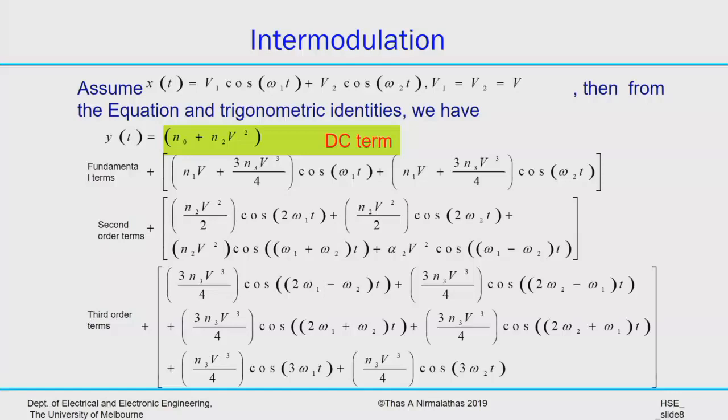Of course, if you design a circuit where the fundamental frequency and second harmonics are within one band, for example, a very broadband antenna looking from, let's say, 1 gigahertz up to 6 gigahertz, we want one antenna which looks at all the mobile systems and Wi-Fi and everything. Let's say we want to digitize everything out there and know who is transmitting what. That's a hypothetical situation. In that case, we want an antenna plus amplifiers looking anywhere from a few hundred megahertz all the way up to 6 gigahertz. So you can see 1 gigahertz and twice that, 2 gigahertz, is part of it, and even three times is part of it. In that case, second harmonic, third harmonic, even fourth, fifth become important, because all of them fall into the same frequency band.